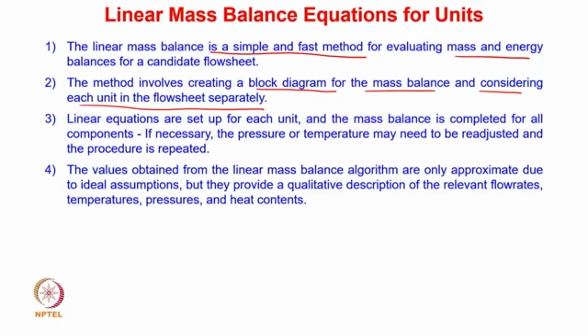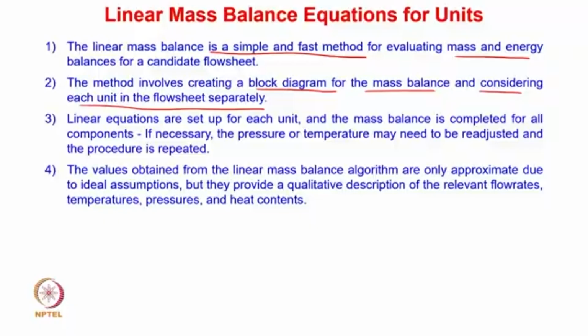So you can see that input and output of each unit we are now representing by using specific equations. So it enables formulating the block diagram, and that helps in combining everything. The linear equations are set up for each unit and the mass balance is completed for all components.